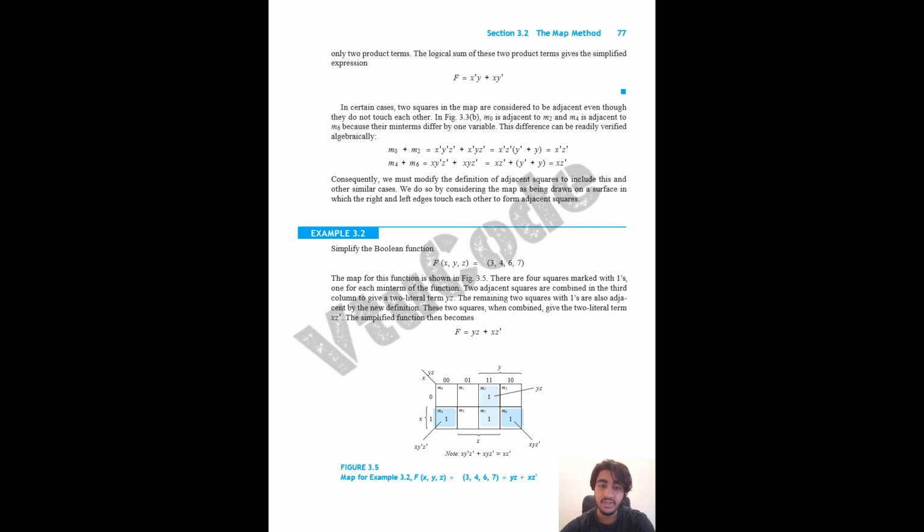Now, how you simplify this K-map is very important. So what are we going to do? In a K-map, we can simplify based on the hierarchy. First we have the oct, that is 8. Then we have the quad and then we have a pair. And if there is no match for it, we go for a single notation. So here we have